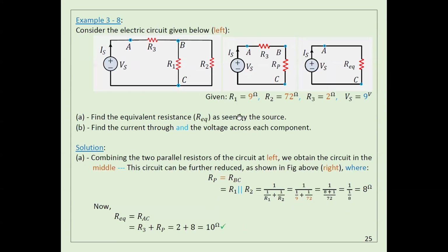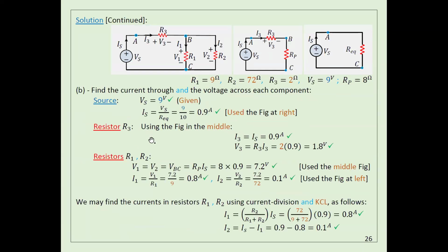Okay. Now, what else do I want to find here? Okay, I want to find the voltage here. Very easy, because you have IS, right? So if I multiply IS by the resistance, I'm just applying Ohm's law. Multiply IS by R3. This gives you the voltage drop. Okay. Yeah, so here V3 equals I3 times R3 equals whatever, okay, 1.84, okay.